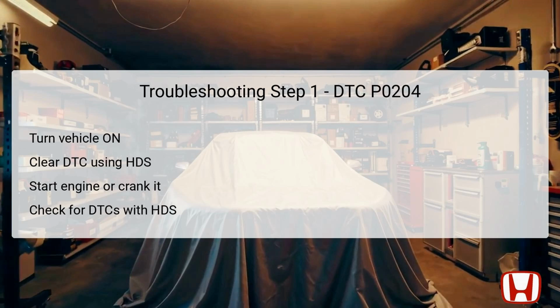Following this, check for any pending or confirmed DTCs using the HDS. If DTC P0204 appears again, this indicates a persistent issue that requires further investigation. However, if it does not appear, the problem may be intermittent, necessitating a check of connections and terminals.